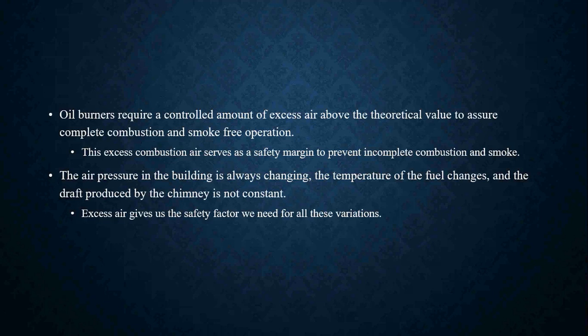The air pressure in a building is always going to change no matter what. Okay, think about it every day. The temperature of the fuel is going to change. The draft is going to change based off of barometric pressures outside and the barometric pressures inside a home. See? So excess air gives us a safety factor that we need for all of those variations.